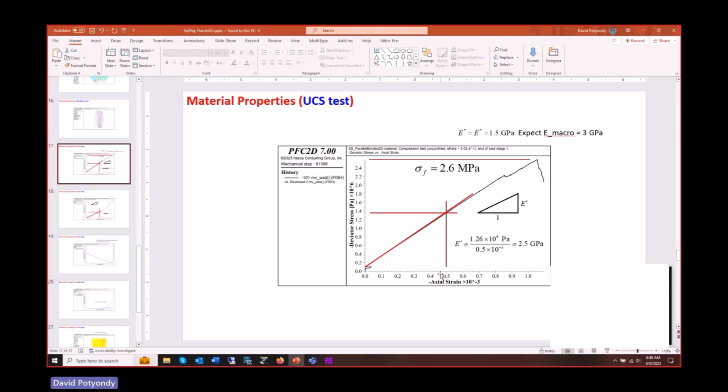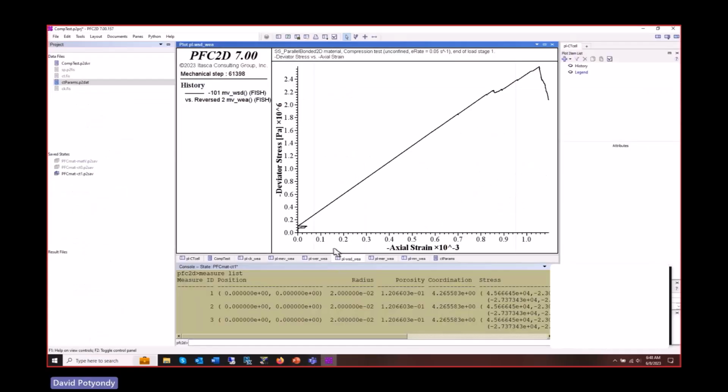In a 2D model, when you get a Young's modulus, you have to assume plane stress or plane strain conditions. Depending on which condition you assume, the modulus will be slightly different, but it only differs by less than about 5%. So for most purposes, this is sufficient. This doesn't occur in 3D. In 3D, it's just the slope of that. Okay. So there we go.